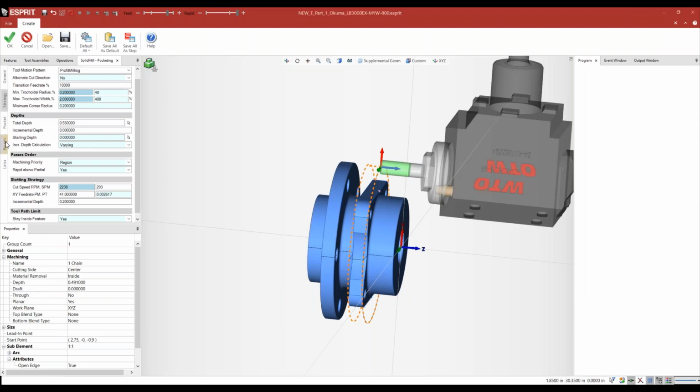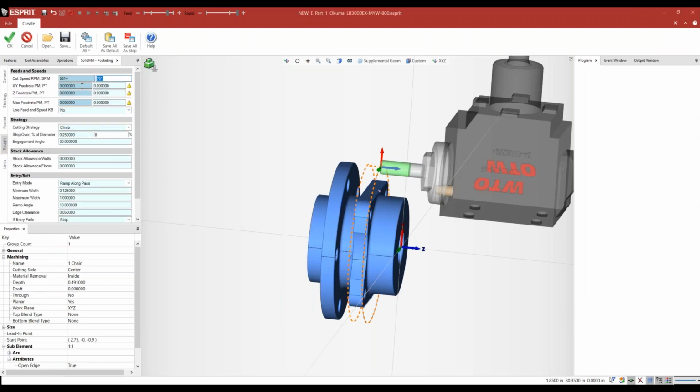So I'm going to go to rough and choose 761 for my speed. Per minute, 269. Same thing for Z. Set this at a very large value. This is for micro lifts in case we need them. My step over, I'm going to set to 8% as it's already set.